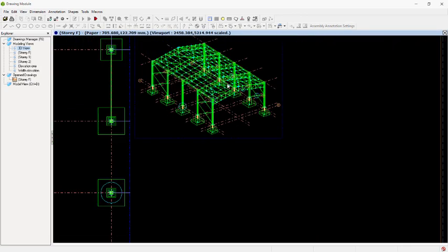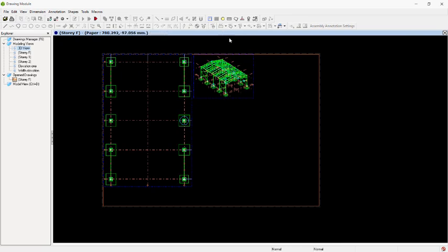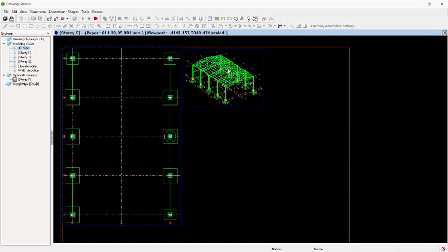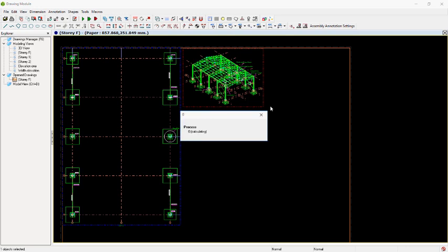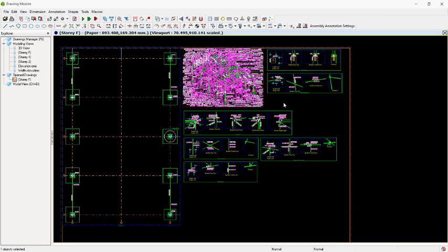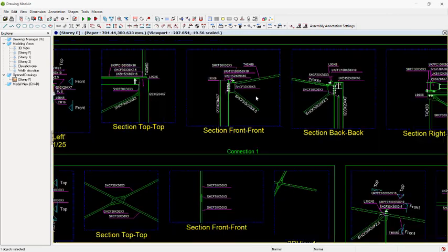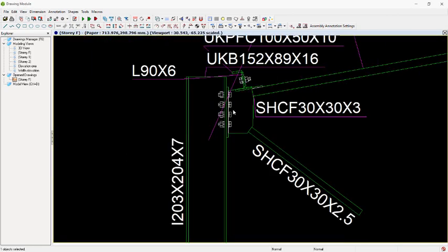Having created these 3D views, now we want to create those sections that we actually formed. So we will come over to this 3D, select this 3D, and click on this. Once you click on this, it's going to create the sections automatically. It is actually loading. All right, you can see all of the sections have been created, so you can see what I was telling you.